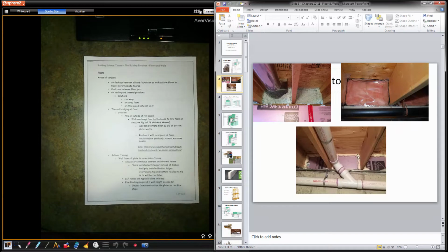And then we have this picture showing that the XPS foam is sealed with spray foam. That should be further out. You see the foundation wall here, no insulation at all. Eventually that's going to be insulated. You'd want that foam to be flush with the basement wall, but for now, it's insulated. So thermal, it has vapor and air properties, all in one cavity. Basically all three of these: air, vapor, and thermal.